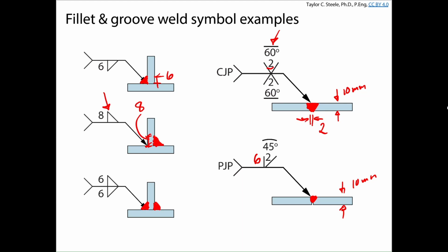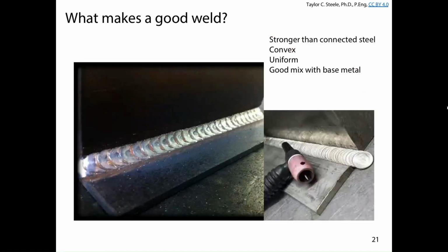Okay, so, well, you generally want it to look something like what's in the picture here. There's a common lingo in welding that if you're doing a good weld, they call it laying down dimes. So your weld should look kind of like a series of dimes, side to the other, with nice, well-defined surfaces. It might not look as defined here, it might be more uniform. Generally speaking, a good weld has a nice-looking surface and it's well-proportioned.